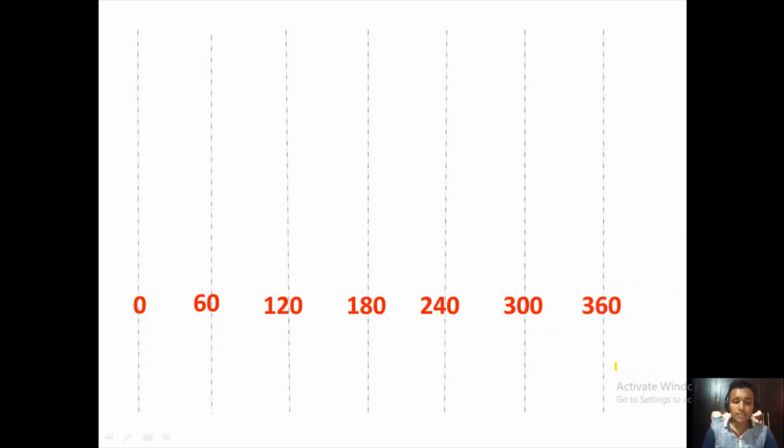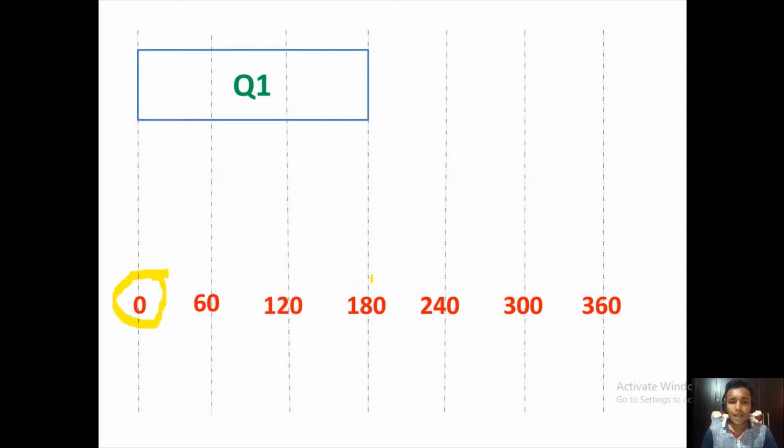Each thyristor operates after every 60 degrees and remains on for 180 degrees, because this is the 180-degree mode of conduction. Now starting with thyristor Q1, it is fired at alpha equal to 0 and conducts till alpha equal to 180 degrees. You can see it is on from 0 degrees and remains on till alpha equal to 180 degrees.